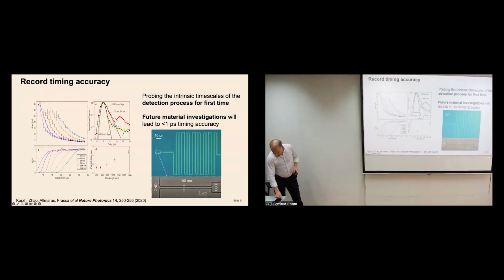So one thing that, when I was at JPL, we worked on understanding the fundamental limits of the timing resolution. So this was sort of how close can we get these two time bins next to each other, particularly looking at the nanowire. This was a really big collaboration with MIT and NIST, JPL. So we made these devices which were very short nanowires. They were only 5 microns long, because we wanted just to see how good is the timing resolution of this very small, high quality device.